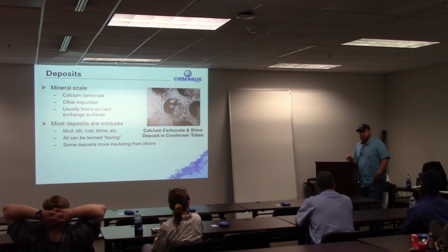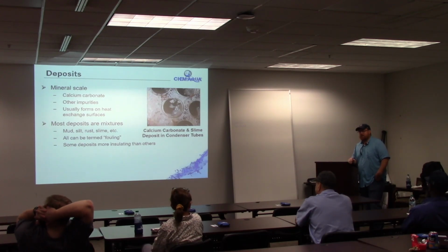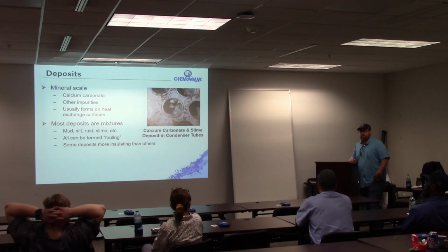If it's smooth metal, that's good. If it's slick and slimy, you have a problem. A lot of people overlook it because they didn't have any scale. Biofilms are actually 4 times more insulating than scale. So if you feel a really slick, slimy tube, you probably have more of a water treatment issue than if you had a little bit of scale in there.